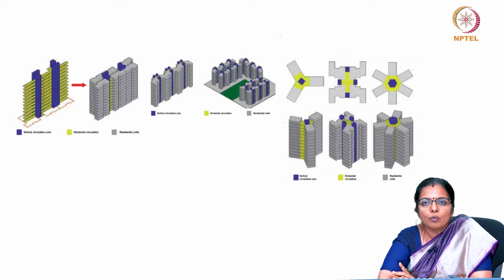So built form which is designed such that it is self-shaded through massing or articulation, resulting in sheltered built forms and cutting off a large amount of direct solar radiation, is most appropriate for hot and dry climate.